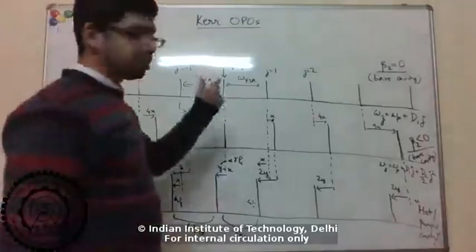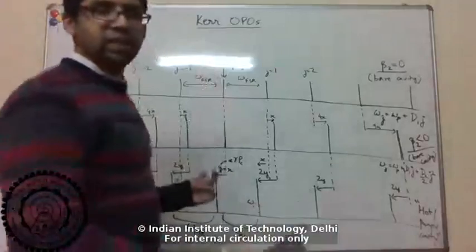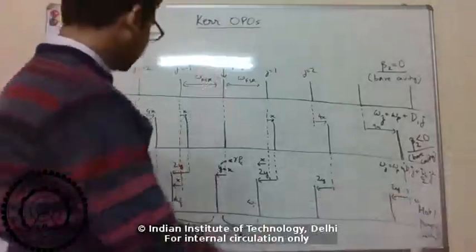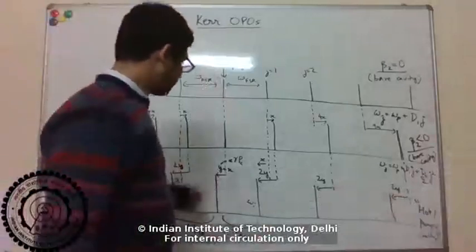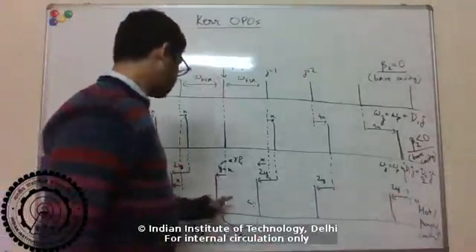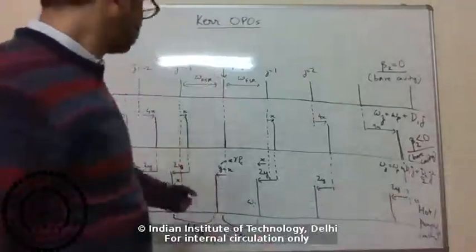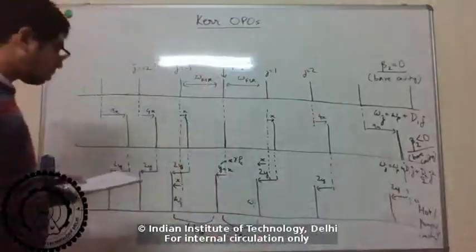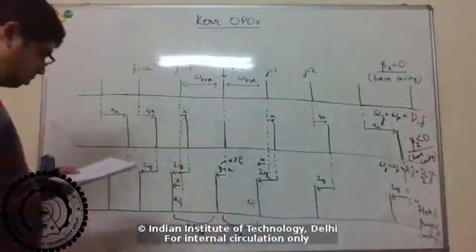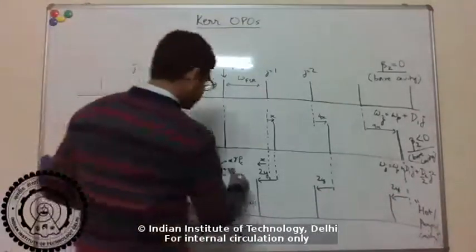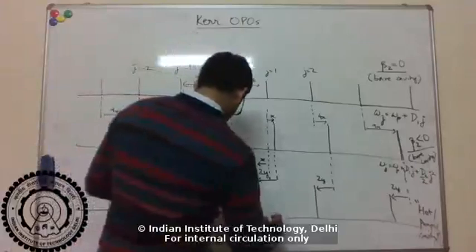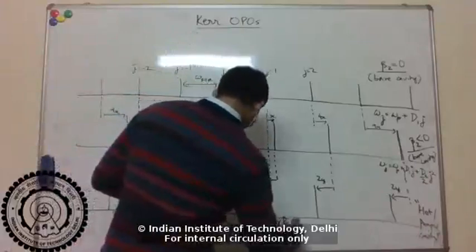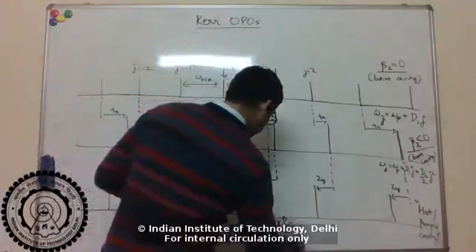Okay, so basically at a particular pump power, the nonlinear phase shifts compensate the dispersion in the cavity, and you get equal spacing, which can get oscillation to happen. Right, so y equal to x. What is that condition here? See, y is gamma P c by n effective.